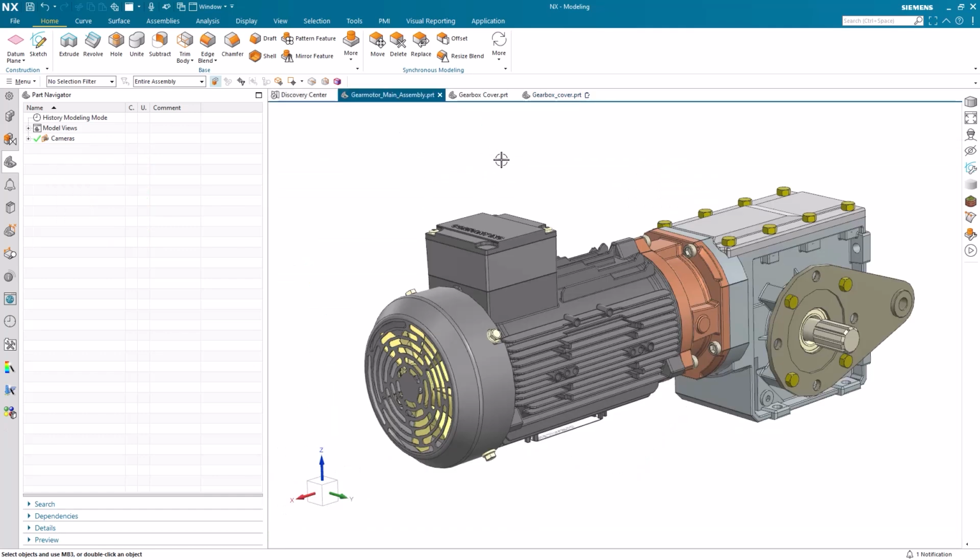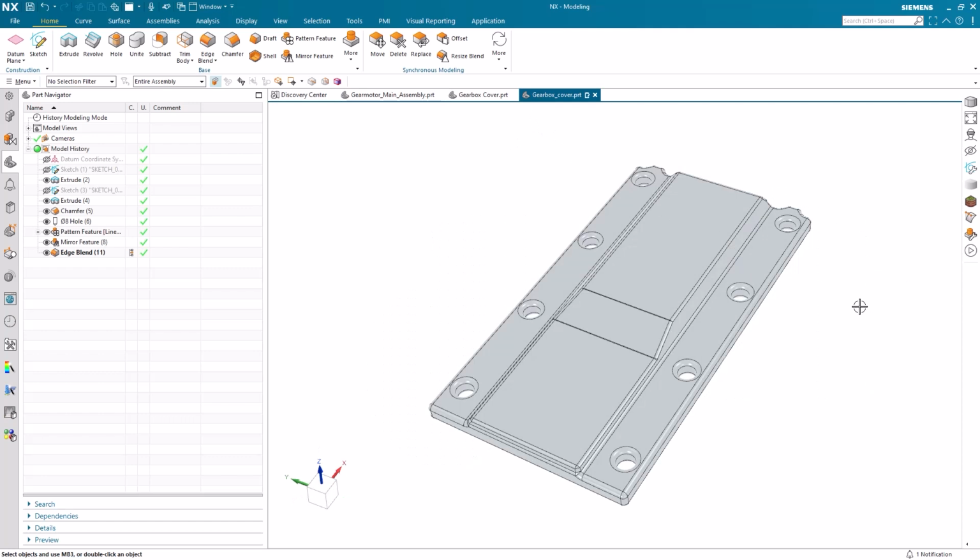In conclusion, in this video, we've reviewed the essential steps for modeling a part for the first time. We started off by looking at how to create a new part file to begin our work. After that, we investigated the basic layout of NX to get a better understanding of where important tools and commands could be found. Next, we began to sketch out the basic shape of our new part, focusing on fully defining our new sketches. From there, we were able to use the extrude tool to produce a 3D product. After that, we refined our end product using the hole command, chamfers, and edge blends.